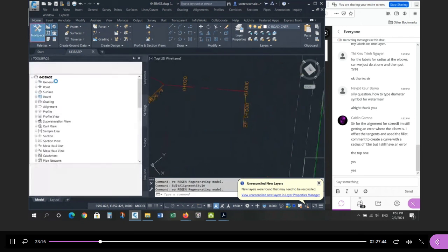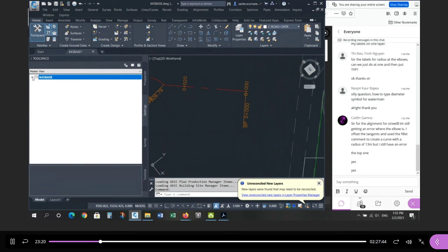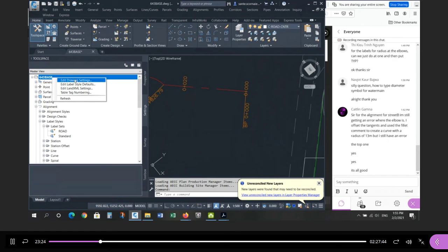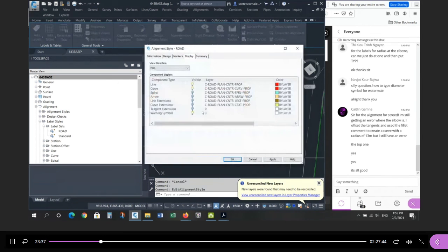The other place to look, let me just check one more thing. Sorry, Caitlin. I've seen this before, and I can't remember exactly what we did about it. If we go to edit the drawing, it won't show up on paper, which is the good news. So if you're confident that it's tangent, all you need to do is turn off that warning. If you go to the label, to the style, turn this off, and then you won't see any warnings.